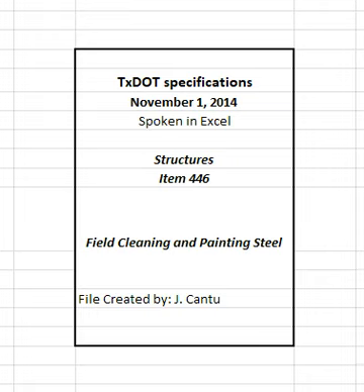4.10 Miscellaneous. Notify the engineer of any condition that may require the repair or replacement of any portion of the bridge. Stencil on the exterior face of the outside beam the control, section, and structure number upon completion of the painting operations for each structure as directed. Stencil on the interior face of the outside beam the completion date of the painting operation. Do this work at each end of the structure where painting is specified.